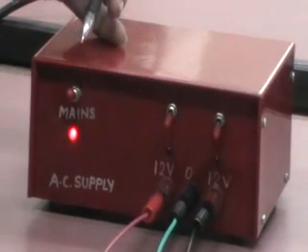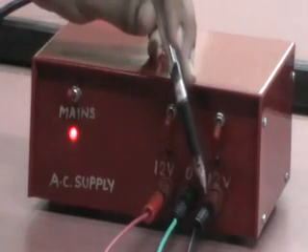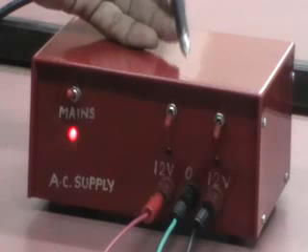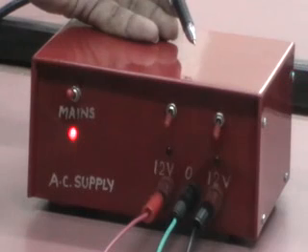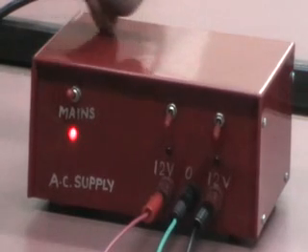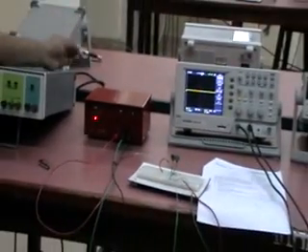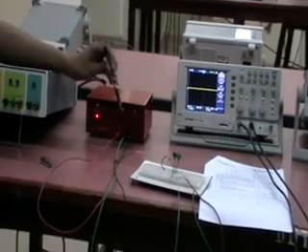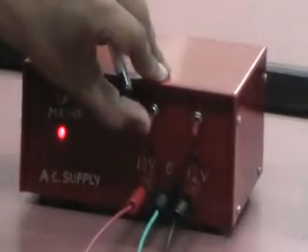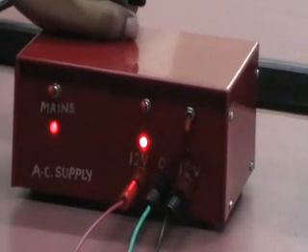This is the one. The red wire is the in-phase component, and the black is the 12 volts out of phase component. In this configuration, the two points will be exactly out of phase with respect to the ground. These outputs are brought out to the sockets on the panel through two switches S1 and S2. Whenever you want to use the in-phase component or the out-of-phase component, we should switch on the particular switch. As you can see, we just make it on. So this is the step-down transformer that we are going to use in the rectifier case.